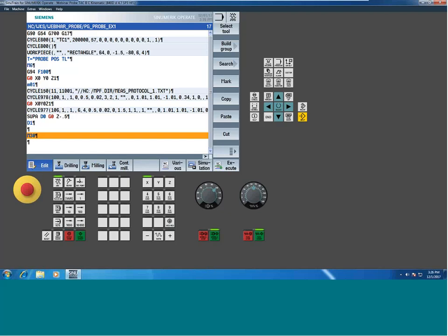don't expect the value to be there, especially after the program has been cycled, because you never know what's going to potentially use an R variable. So I would say during the length of the program, if you want to dump to an R variable and then grab it and do something with it, by all means. But I wouldn't write to an R variable if you're expecting to then get to that variable, I don't know, 3 jobs later, let's say.